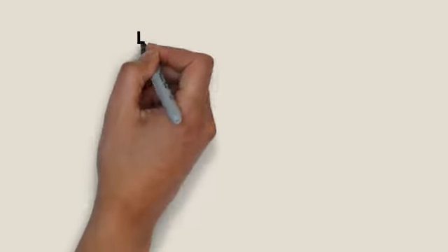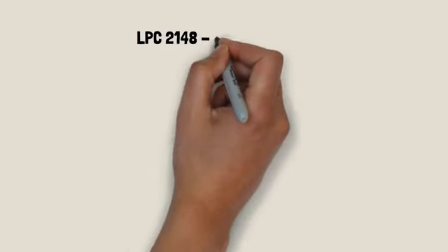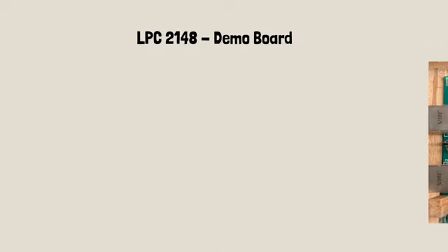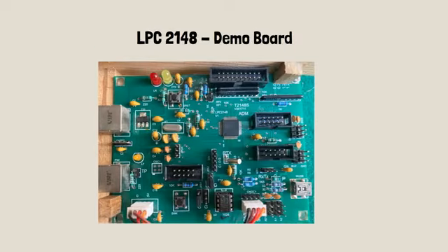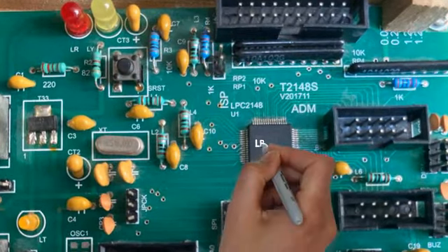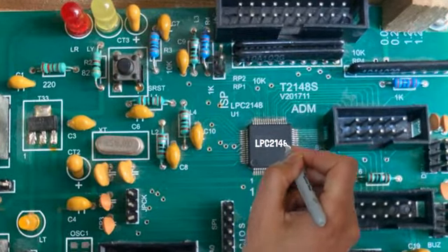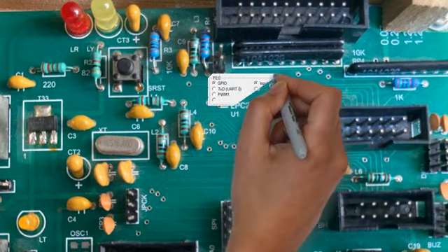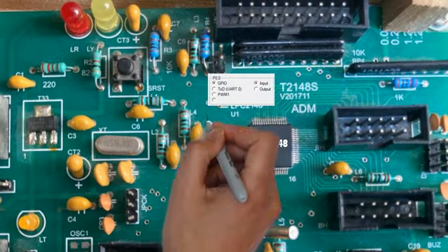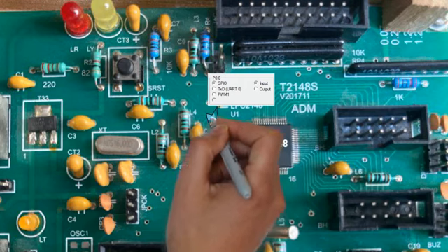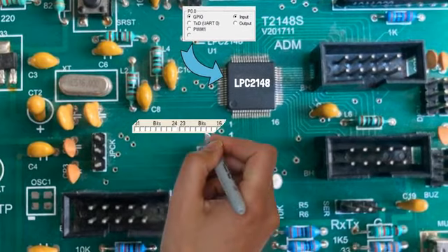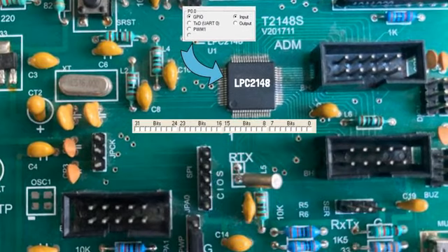The most important part of our embedded system will be LPC 2148, which functions as the brain of the system. LPC 2148 is available in a small LQFP64 package. Each pin is multifunctional and can be programmed as input or output. Each of these I/O pins can be either digital or analog. ARM7 registers are 32 bits in size, and it can read or write 32 I/O pins in one cycle.